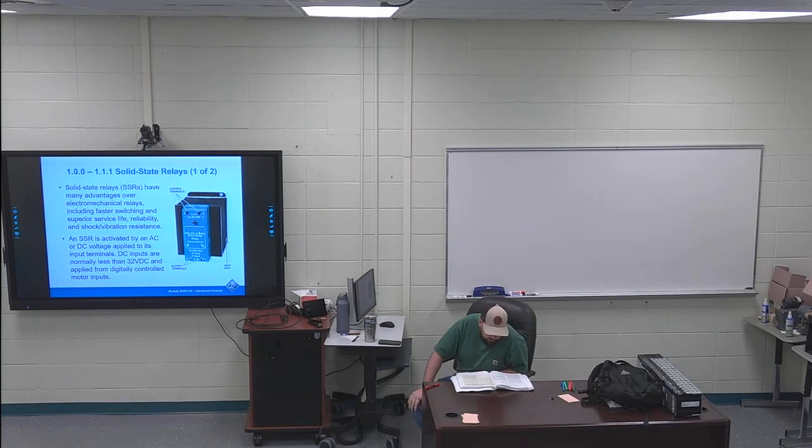Page 3, they go through and talk about the comparison chart for electromechanical relays versus solid state relays. So like the coil voltage and control voltage are comparable in those two. Inrush voltamps or control current. The row that I've highlighted is the second to last one. Where there's no equivalent in EMRs for SSRs, they have the ability to do zero current turnoff. So they can turn off at essentially zero crossing of the load current that flows through this solid state relay.